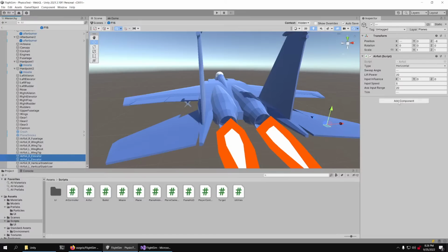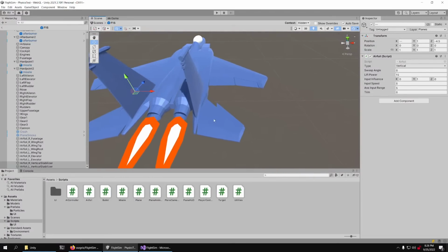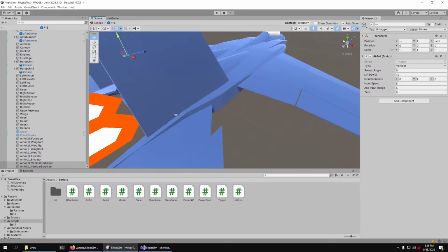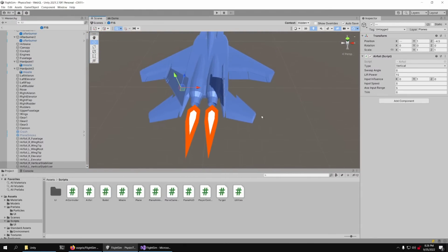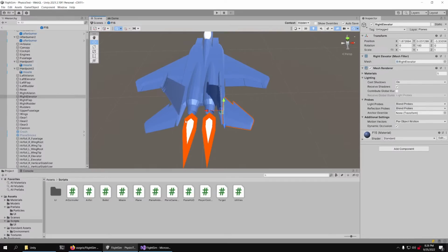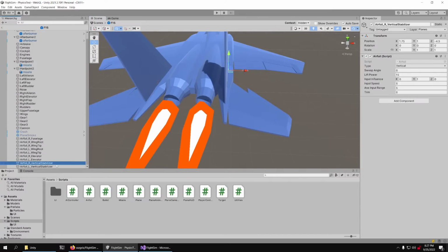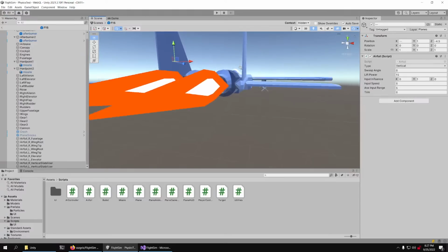Oh, I set the trim on the elevators to different values. That's what was causing it to roll. On the F-15 in particular, the elevators can also be used to roll the plane, not just the ailerons. So you'll see on real footage, the elevators will turn in opposite directions to help roll the plane. What I was doing was accidentally rolling the plane because I had different trim settings on them. Okay, so back to the rudder problem.